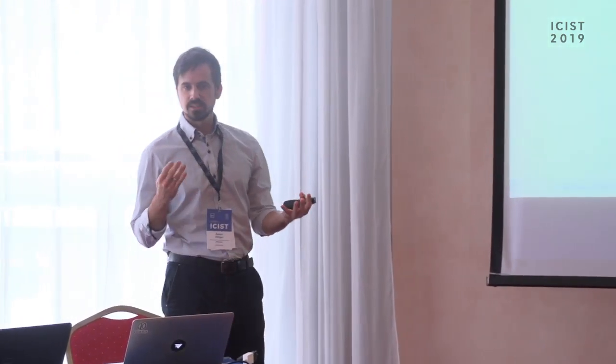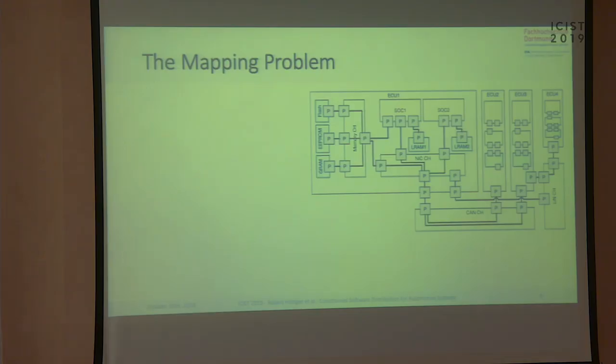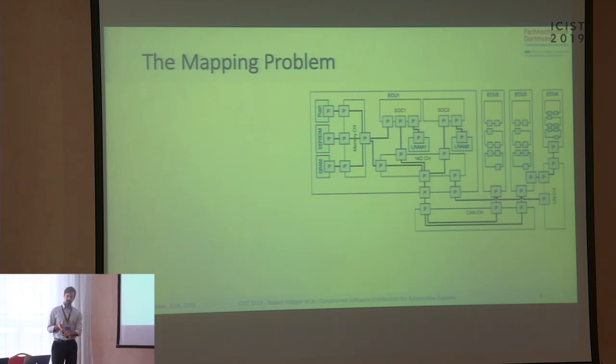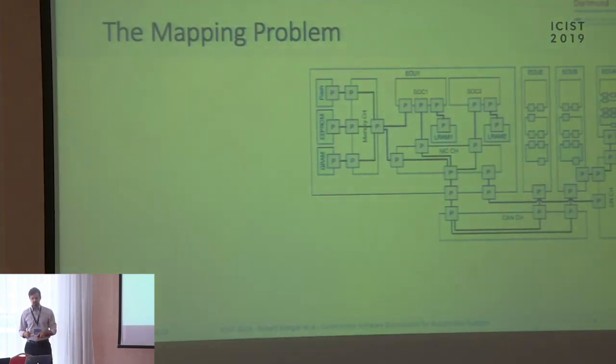And all those ECUs can be of different sizes. They can have multiple processors. They can have heterogeneous processors, so processors with different speeds and of different types, like CPU or GPU. And this not only relates to the processors, but also to the type of memory or the communication bus. Like if you have a Controller Area Network, a CAN communication, a LIN bus, SPI bus, or whatever you have in the car. So it's a highly heterogeneous system consisting of many different ECUs and many different processors.